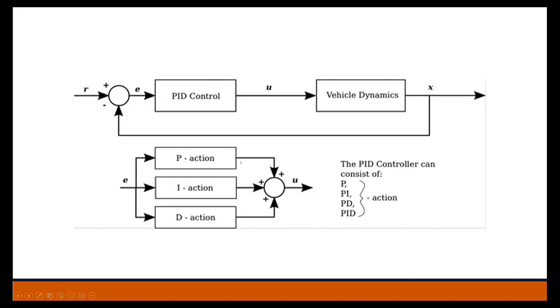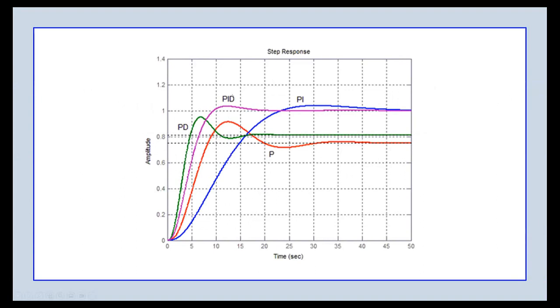These different controllers provide different filter effects on the control variable, and because of the difference in control filters, you have different times for reaching stability. The proportional one is slower to reach stability, and there's a systematic error: it doesn't reach the value you want.